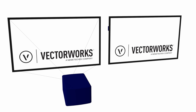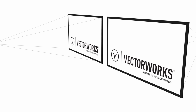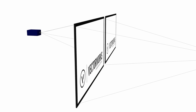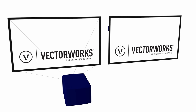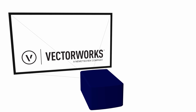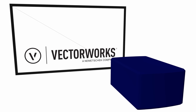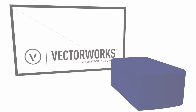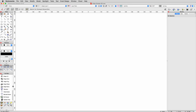Video screen objects are composed of both a 3D screen with an image applied to it as a texture, as well as an optional front or rear projector. The image shown on the screen can be customized with your company logo or any other image you might need. It comes with a number of standards included by default, but most of these can be customized to suit your needs. To insert a video screen, first select it from the Spotlight toolset.